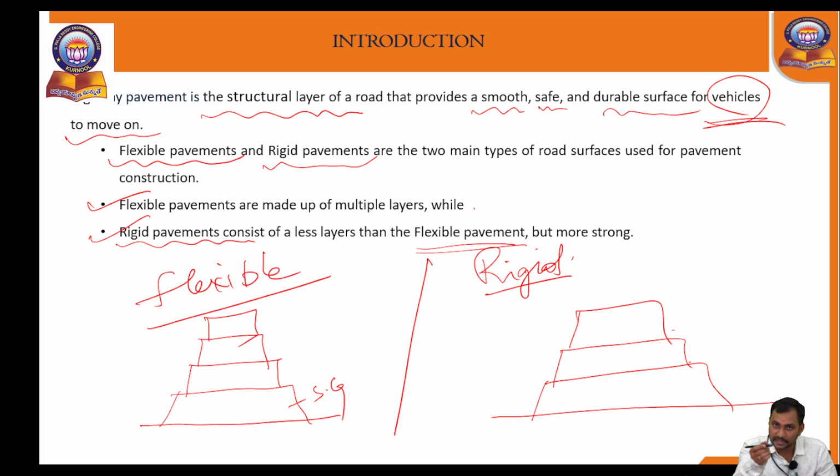In the same way, a road surface should not be constructed directly on the ground surface; it should come from the base, under the ground. That under-the-ground layer is the subgrade layer. Next, the second layer is the sub base layer, the third is the base layer, and the last is the surface layer.